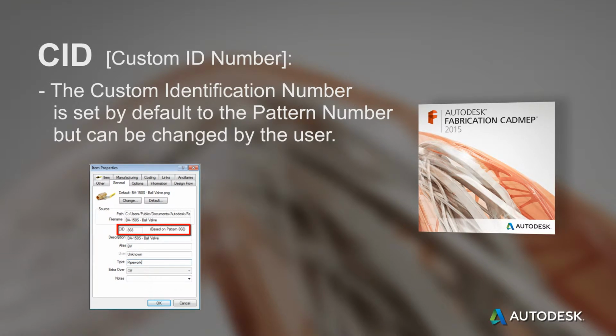CID. The custom identification number is set by default to the pattern number but can be changed by the user. The CID number can be found for each item by using the Fabrication CADmep Properties command. The source pattern number is displayed to the right of the CID.